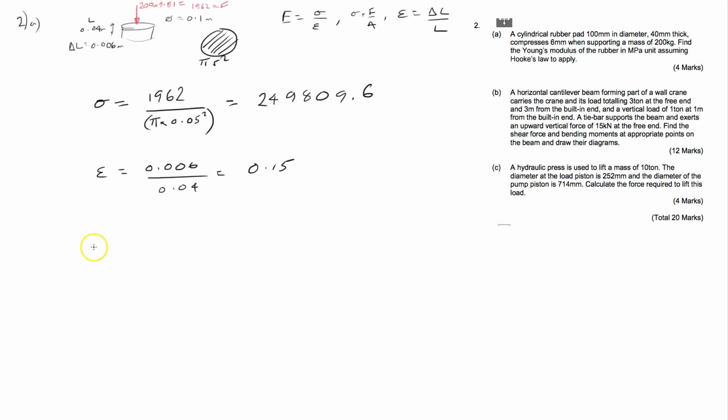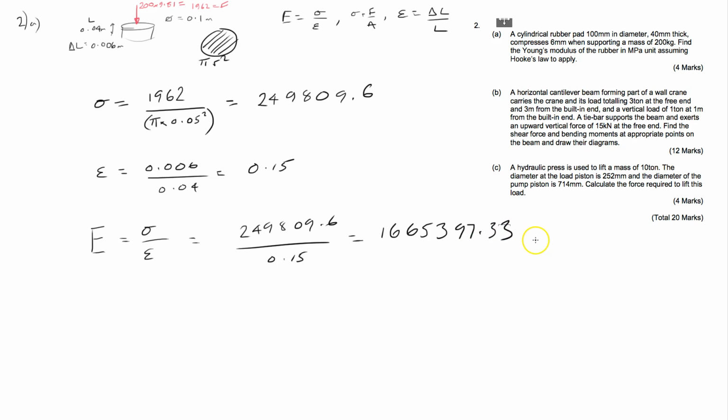And to calculate Young's modulus, that's going to be stress over strain, which is going to be equal to 249,809.6 divided by 0.15 is equal to 1665397.33, pascals.